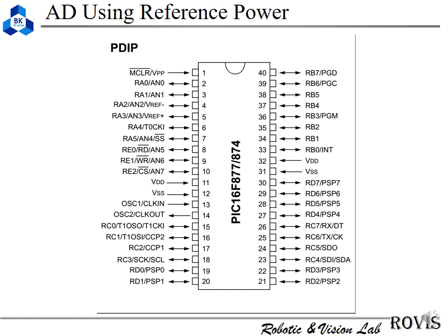In the AD converter, we have another very popular case. The voltage here we use is 5 volt, but some sensors just use 3 volt as the maximum voltage. So we have to connect it as the reference power for reading AD.